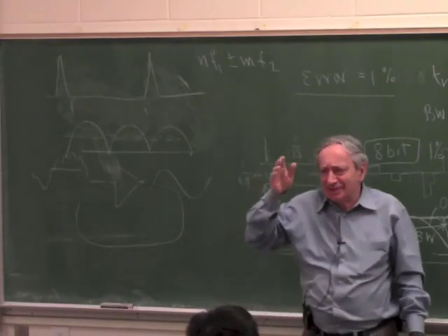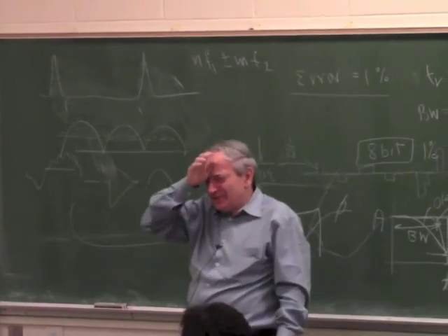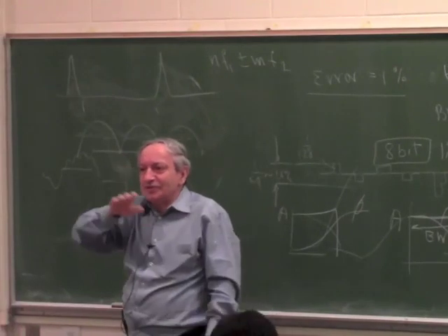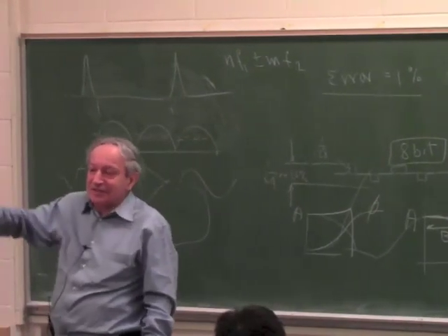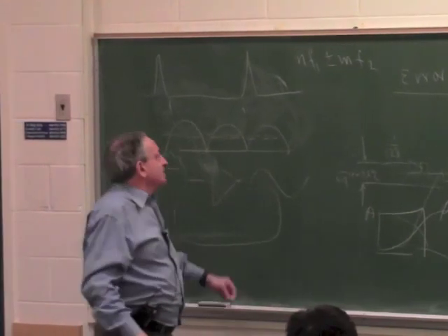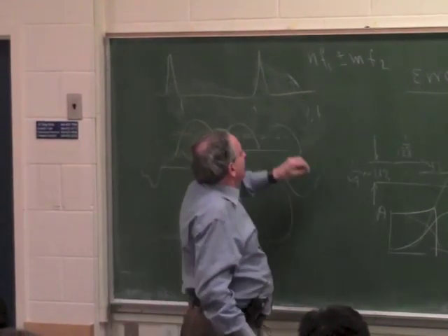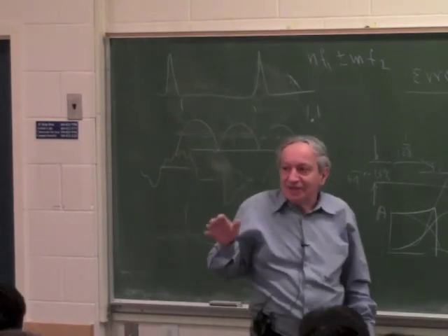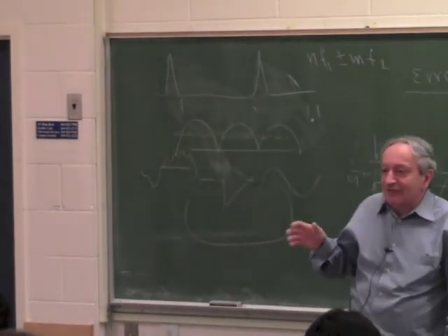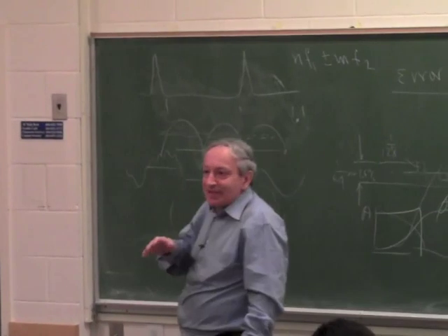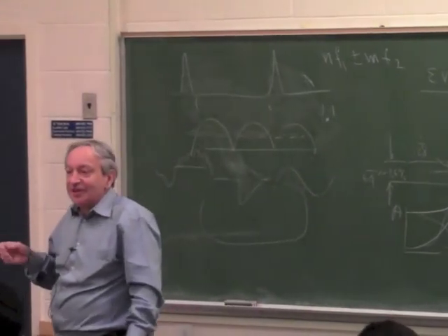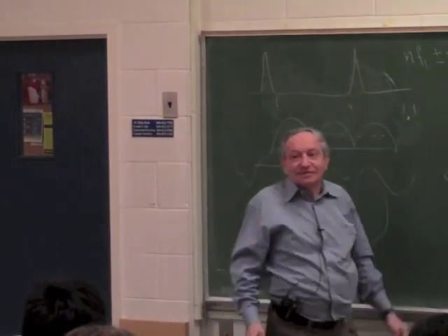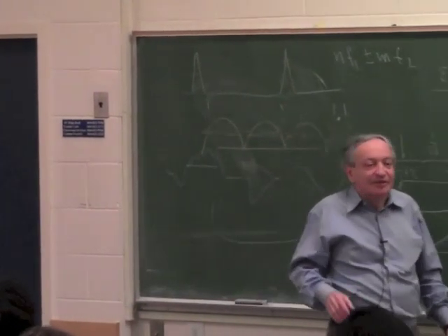It has to do something with pi, 2 over pi, I think. If you integrate the sine wave, find the average, then the ratio between them is roughly 1.1, so for a sine wave it's not bad. If you rectify a sine wave and mistake the average for RMS, it's only 10% error, okay? But if you're dealing with pulses, it's a very dangerous mistake to make.